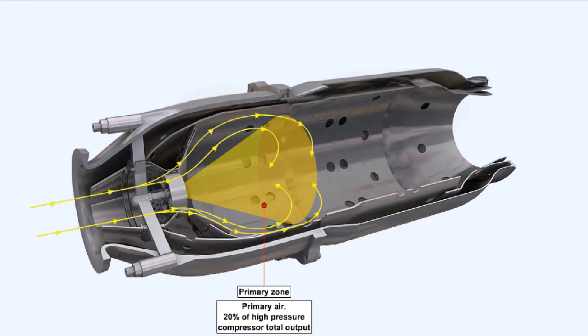This is the air which is mixed, in a ratio of approximately 15:1 by weight, with the fuel and burnt. By being passed through the flare and the swirl vanes, the velocity of the primary air is reduced, which must happen if the flame is not to be extinguished, and the shape and position of the flare and swirl vanes also starts the air recirculating within the region.